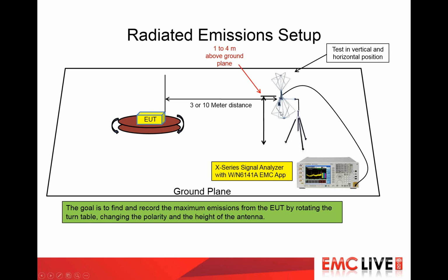You can take and rotate your antenna, but you need to be sure to also spin your device. So they will check at many points as they turn this device around. You can use a table, or you can just rotate your device around. Some items that are very large, they'll actually put a bunch of antennas around a device like an automobile. So there's a lot of testing with automobiles nowadays because of all the RF products in there. They'll test those with multiple antennas around them and connect it up to a test set.